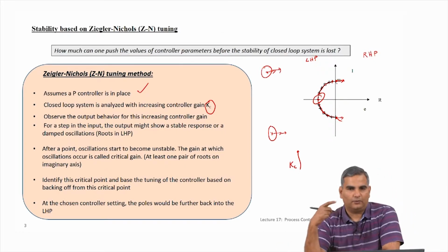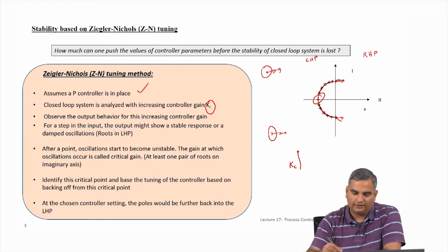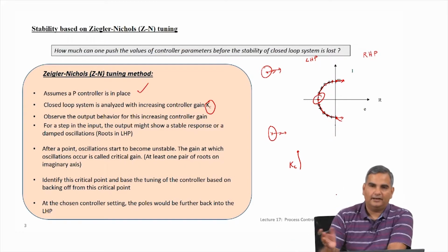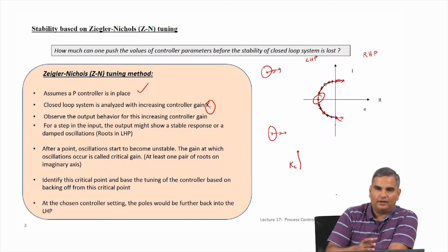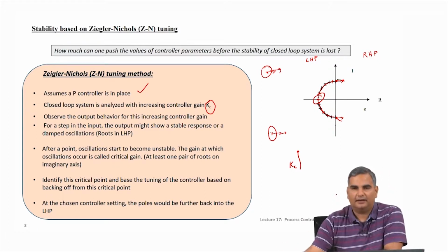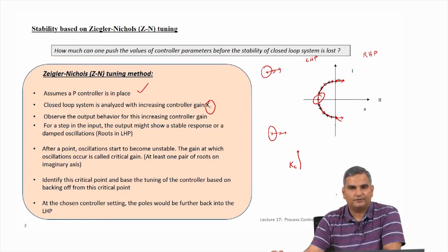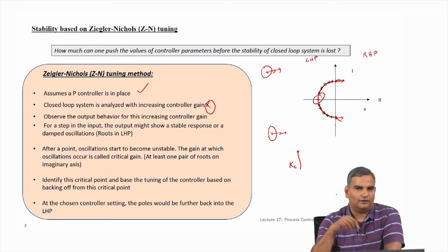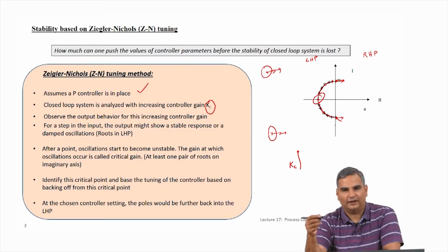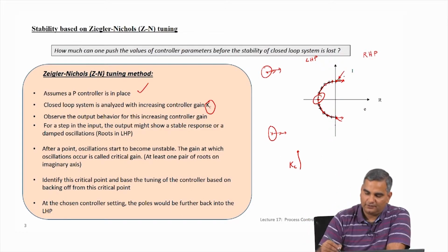So, remember the mountain example I gave you, this is the point, the edge of the cliff, right. This imaginary axis is the edge of the cliff. Anytime I am away from here, I do not have to worry about what happens, and anytime I come to the right half plane, I have to worry about it. So, the edge of the cliff is really the imaginary axis, and the point that we are saying is if you are continuously walking from ground and suddenly falling off, you have to touch the edge of the cliff first before falling off, right. So, this is the limits of stability.